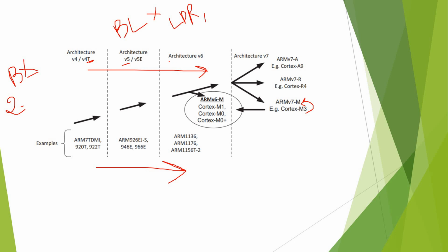The big change, let's say, an update that ARM did, was introduced in the ARMv6 architecture. Here we have two subsets. We have the mainstream ARMv6-M, and we have what is called the ARMv6 T2 architecture. T2 here stands for Thumb-2. Before, we used to have 32-bit instructions, referred to as ARM state when the CPU is executing 32-bit instructions, as well as 16-bit. But this is not really mixed from a hardware perspective. So there has always been this distinction between ARM and Thumb 1 state.